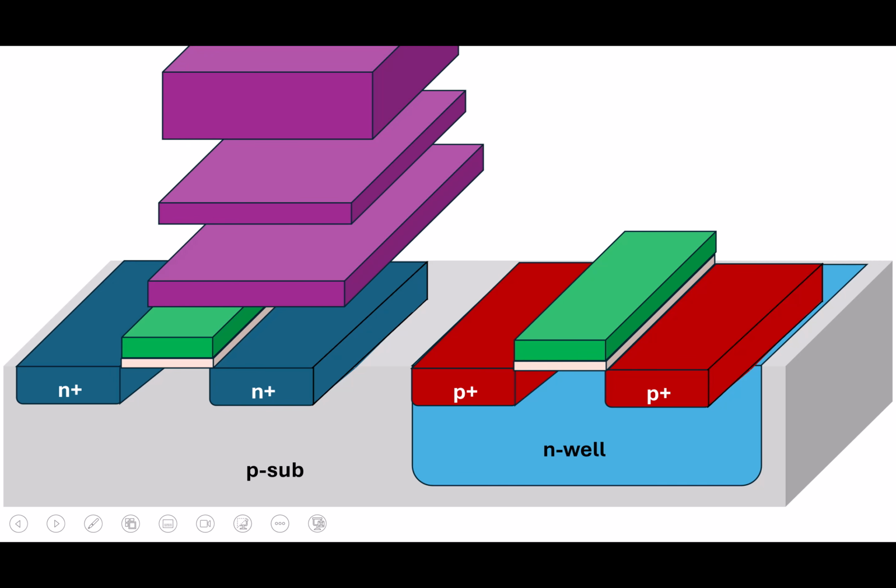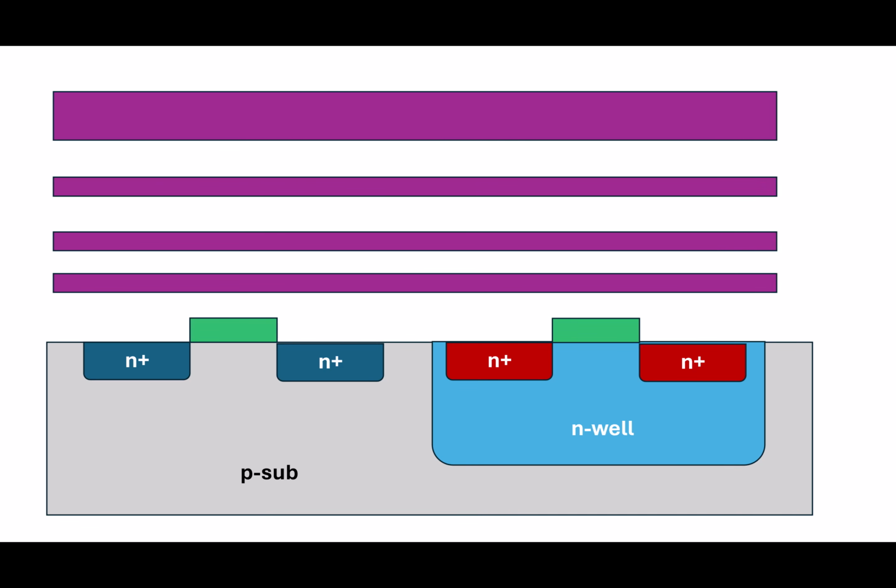So same thing. You have multiple copper metals like this, and in fact you have multiple layers depending on the process. There can be 10 or 12 also. So these are copper, and typically most processes now have an option to have one aluminum metal layer also, but all the other layers will be copper typically. And again, these vertical heights are not under your control. So here again showing that side view. So let's assume that this is metal 1, metal 2, metal 3.